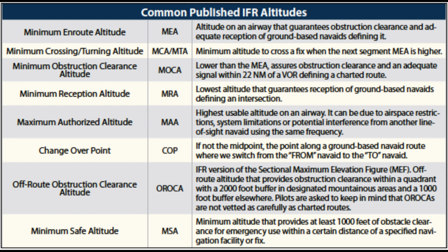Minimum en route altitude, MEA. The MEA is the lowest published altitude between radio fixes that assures acceptable navigational signal coverage and meets obstacle clearance requirements between those fixes. The MEA prescribed for a federal airway or segment, RNAV or high route, or other direct route applies to the entire width of the airway, segment, or route between the radio fixes defining the airway, segment, or route.